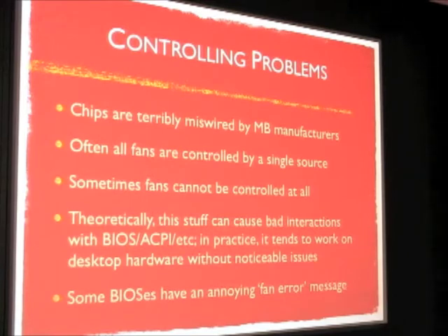And some BIOSes have an annoying fan error. If you make the fan run at a lower speed than it usually runs, when you reboot the system the setting still stays in the hardware monitoring chip, so the fan is still running at lower speed. Some BIOSes check the speed of the fan when rebooting, so if the fan is running at very low speed, it may give you a fan error instead of continuing with the boot process, and it may stop rebooting.